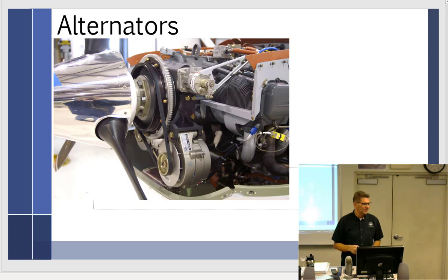So I know on aircraft, at least in this picture, there's one belt driving the alternator. Yeah. Compared to automotive, where one belt can drive like six different accessories. That's like a 17 belt. Yeah, I'm not familiar with any aircraft that uses a serpentine belt, unless it's like some of the light sport aircraft. Well, I guess our 172 out there has a serpentine, but it's also got a Mercedes-based diesel engine conversion. Your Lycomings and Continentals do not.